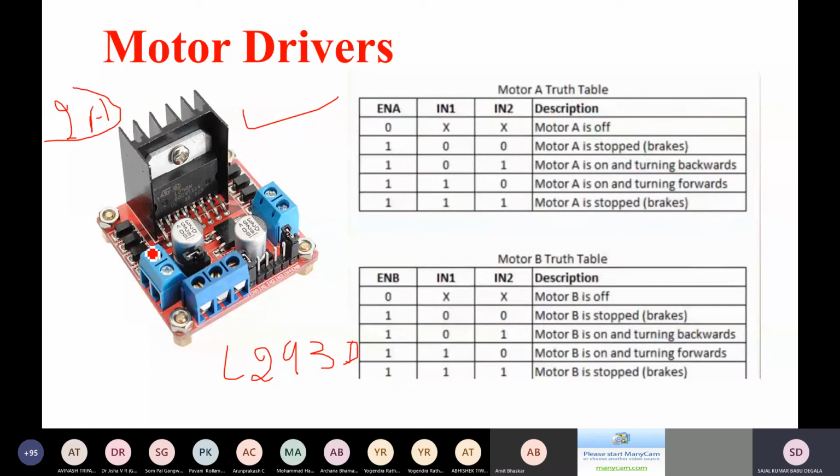But if you are using a PMDC motor, which we normally use in our wheelchair applications, there the motor is going to take a current of 10 amps, 15 amps like that. So there I am going to suggest a motor driver that is the MD20A. So this I have written here. This is the MD20A. The 20A itself represents that it is capable of carrying a current of 20 amps. So you can easily control a motor there.